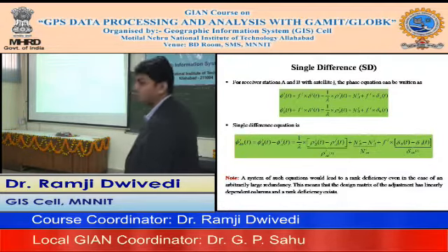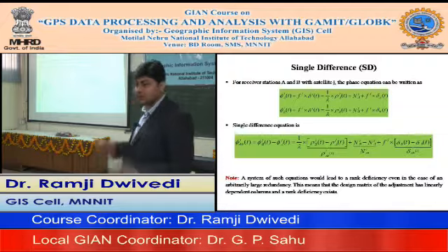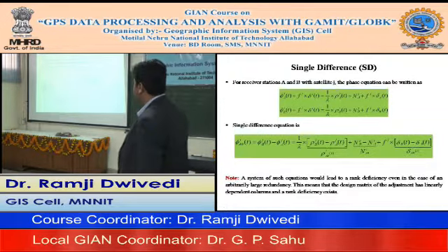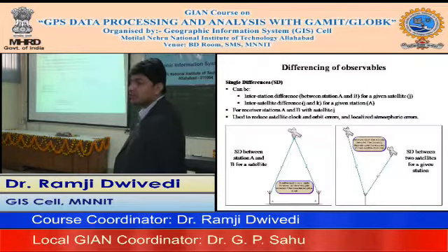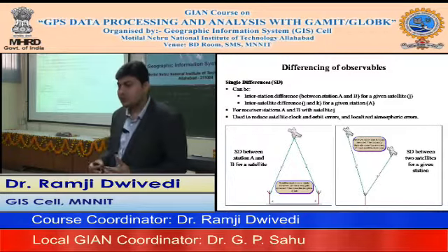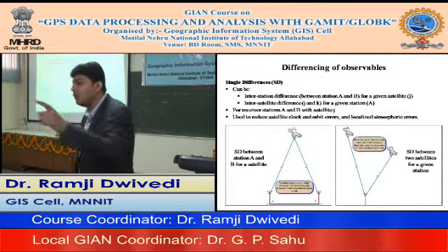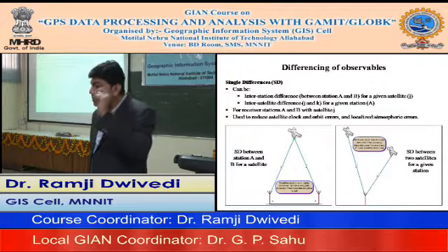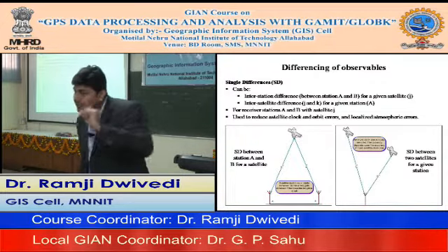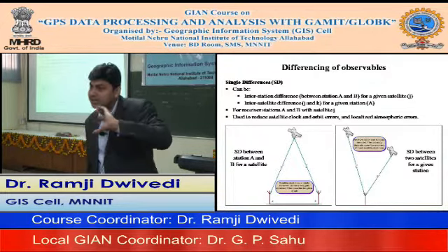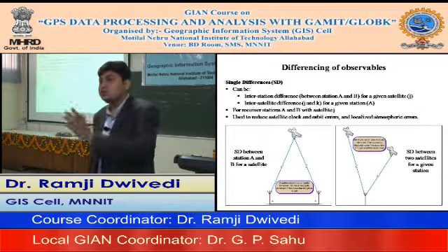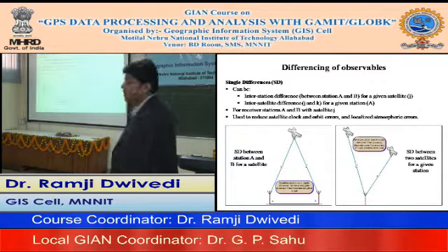So we have to use those reference networks also, and we'll see how to use those base networks for positioning. So there is a single difference between satellite station A and B, and please remember your baseline length, which is eventually the distance between your base and rover, is actually playing a role in your estimate. So please be careful when you read the literature on how to make a session useful; you have to understand that this baseline is playing a role. Okay.